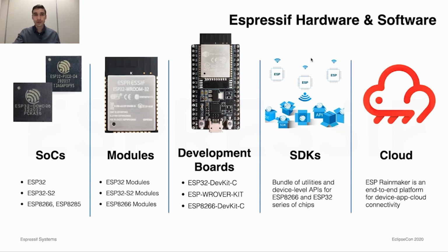Next, on the software side, Espressif provides free software development kits, which can be downloaded from GitHub for all of our products. Typically, these SDKs are built around a real-time operating system, and they include other prerequisite libraries such as bootloader, peripheral device drivers, wireless and TCP/IP stacks, file systems, and some high-level protocol libraries. I'll tell more about one of the SDKs, the ESP-IDF, in a minute.